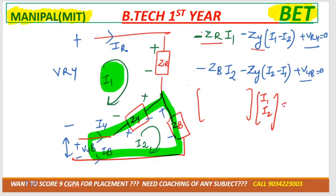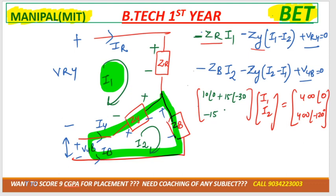I1, I2, and the voltage goes to the right hand side: 400 angle 0, 400 angle minus 120. Solve it and tell me the coefficients of these. After solving, you will get 10 angle 0 plus 15 angle minus 30, then minus 15 angle minus 30, and here minus 15 angle minus 30, and here 15 angle minus 30 plus 20 angle 45.